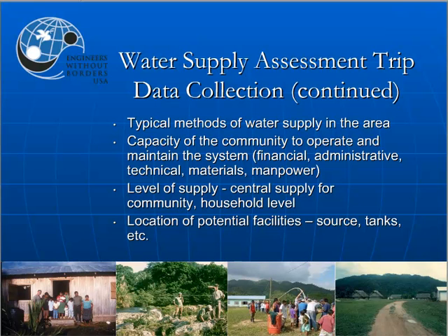So you want to look for that and then make sure that for the location of those facilities, you have all the information you can about those facilities. So let's say a potential tank location, you should have that photographed from absolutely every angle you can think of. You'll want a topographic survey of the site, and you'll want detailed soils information for that site so that if you end up putting a tank there, you'll have all that information for your analysis and design.